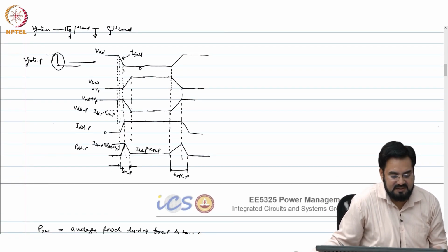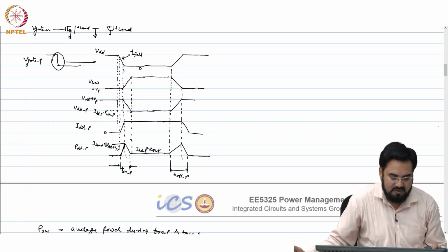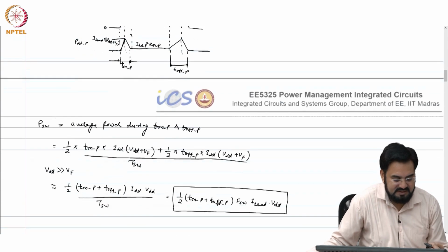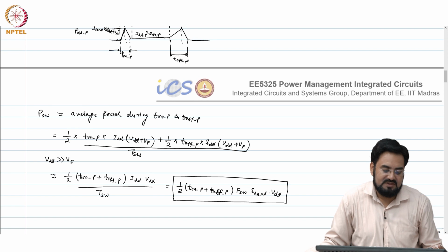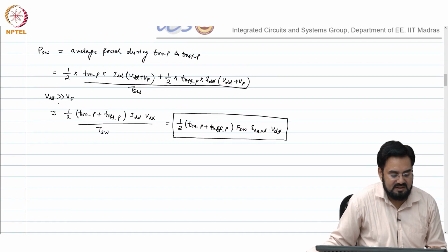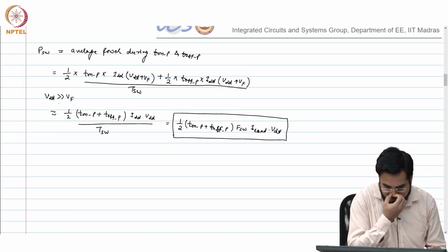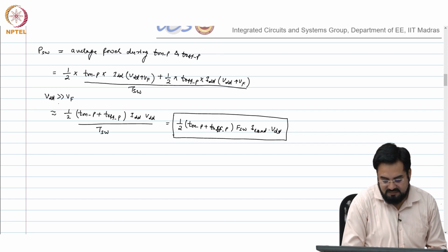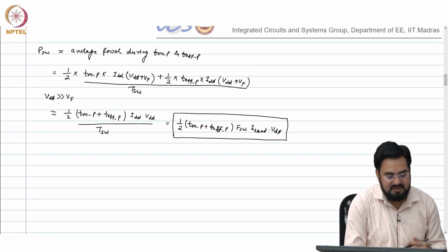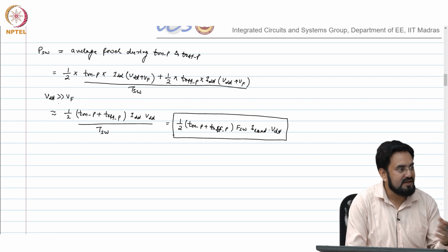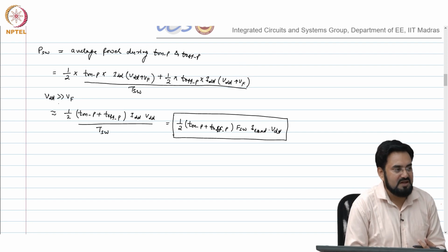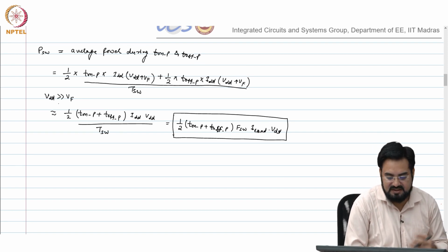Okay, so, for discrete power supply design, what power electronics guys do, they usually consider this as a dominant factor. So, the switching losses start dominating for them. So, all the switching losses, which is your dead time, your gate driver and this particular one, they will start dominating when FSW is very high. Okay. Some of them are a function of load and some of them are not, like your gate driver switching losses, but they all are a function of your switching frequency.